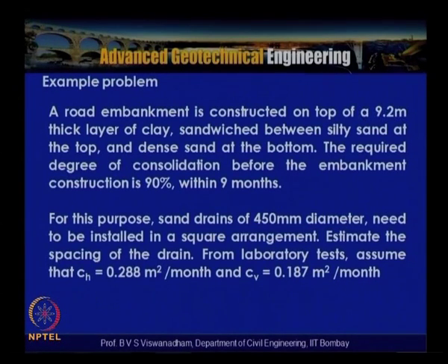And here, in addition to what has actually been asked, we also calculate for the triangular arrangement, so that the layout of the sand drains can be compared in this problem, wherein the procedure is very similar. So what you need to calculate is the time for 90%, then the vertical consolidation, and afterwards UR, and then the TR, the time factor, in terms of some constant divided by n square.